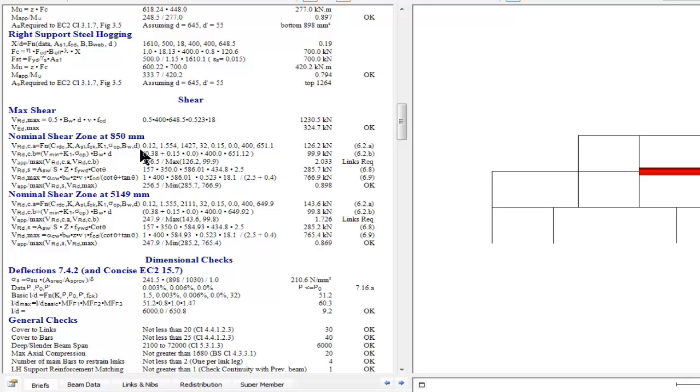In the Eurocode, your capacity is the lesser of the concrete and tension reinforcement or the shear reinforcement. You don't combine everything together. So you actually have to be sometimes a bit more generous on your links. It's a wee bit complicated. And then we have this thing called cot theta that comes into it.